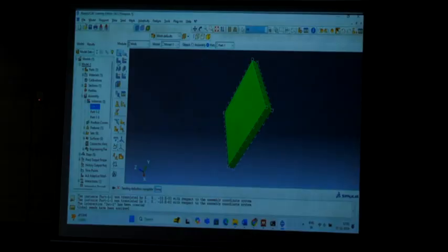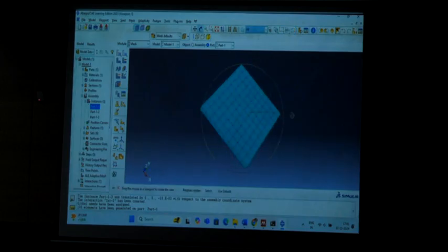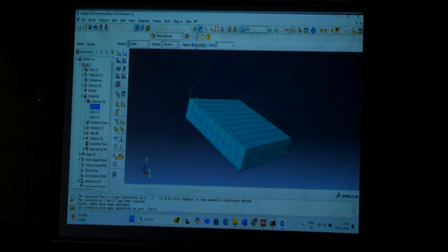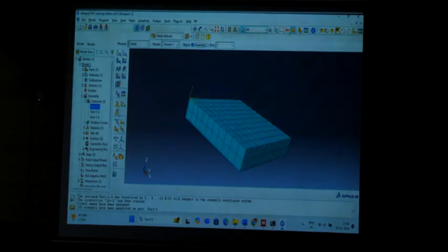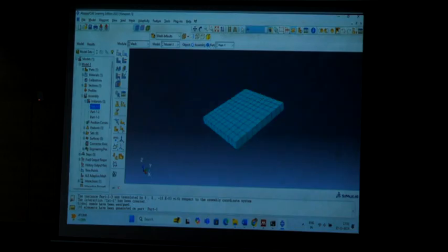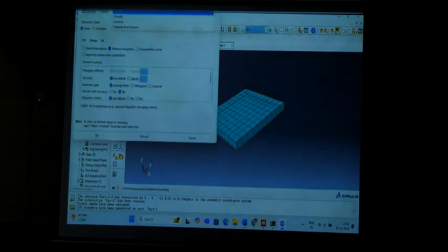It was done, and we will see the part. It was meshed. Meshing was completed for the single one. If you choose the assembly, then it will automatically take for all the nodes, because we have already copied it from each one. Again we have given the size, and now we choose the element type you want to give. If it is transient and these things, we just want to assign which type of mesh element.